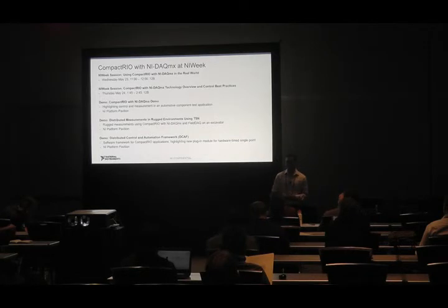So one thing I didn't call out, but the path from FPGA to the processor has increased. Previously, for these products, we were about 250 megabytes per second. For the new controllers that we have, we've actually updated it to now you can see closer to about 400 megabytes per second throughput between the FPGA and the processor.